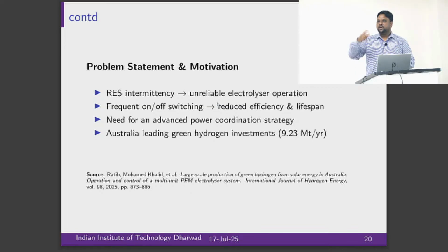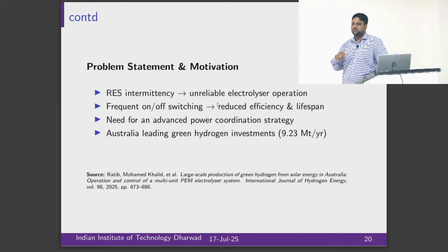That means if the power fluctuates too much, it will directly hit the limit of each electrolyzer capacity, upper or lower. Sometimes it's higher or sometimes lower due to low power. So the electrolyzer, including the power electronics, has to be switched on and off frequently. And that frequent switching on and off will directly affect the membrane and the electrolyzer electrodes.